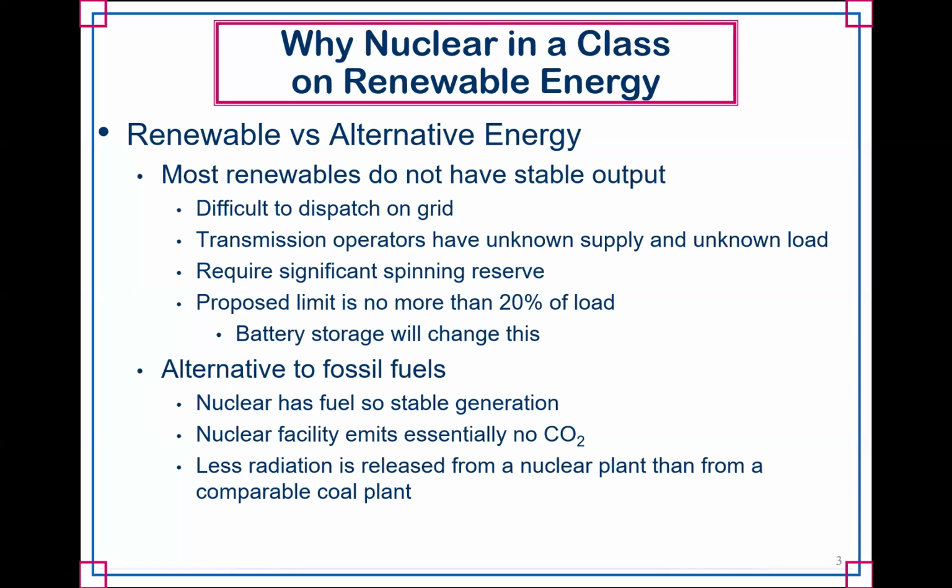And one of the things I failed to mention is renewable doesn't necessarily always mean it's not dispatchable. For example, hydroelectric facilities, those tend to be pretty well dispatchable because you have a pretty good idea that you have water in your reservoirs. Now, if it's going to be months or so with very little rain, that can be more problematic, but you get the idea that there's just more of a short-term question in terms of dispatchability.